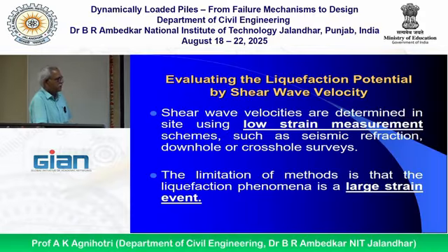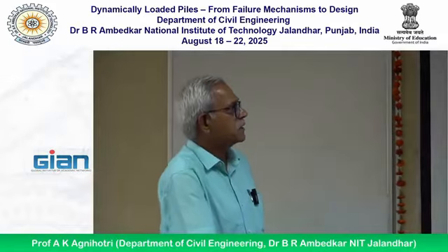The limitation of the method is that the liquefaction phenomenon is a large strain event, whereas these tests which we are performing are low strain measurements, while an earthquake is a large strain event. So error will be there definitely. So that's why it is not a very popular method.